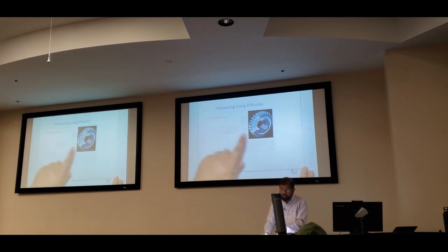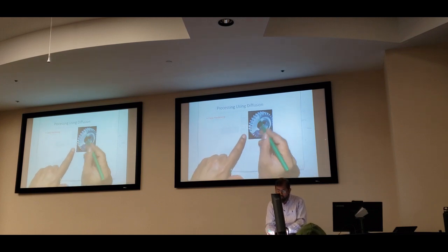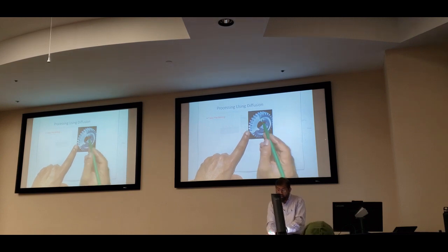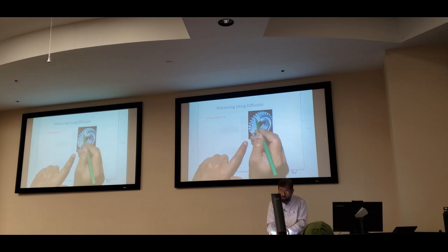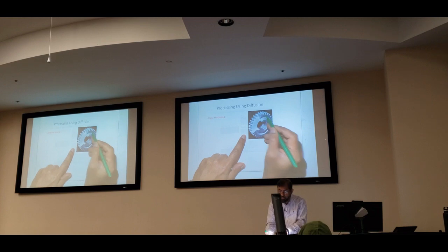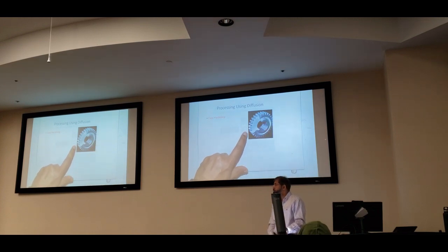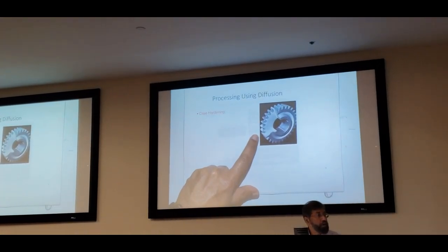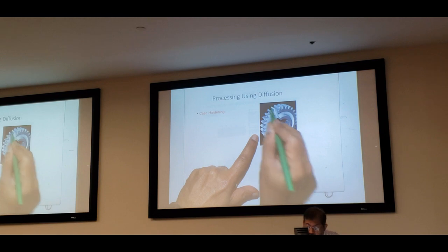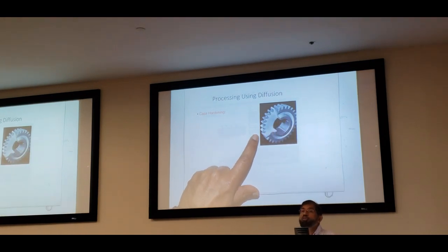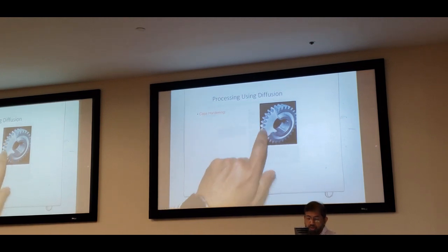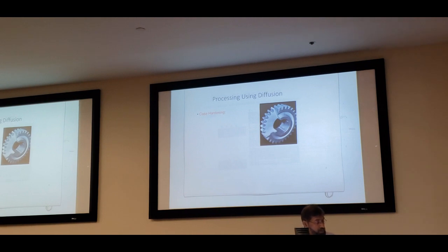Case hardening is a case where you have this gear made up of a certain steel, and what you do is you diffuse more carbon into the outer surface of this gear. Why? To make it harder. To make that outer surface harder, you need to diffuse more carbon into that steel. So that is a very good example of case hardening.